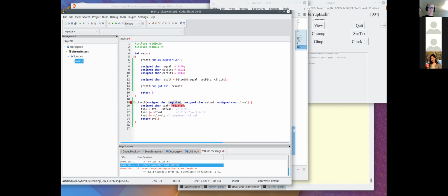So you can actually tell C that this variable belongs in a register. And we don't want to go there. So we're going to call this, let's say, HW register, because it's a hardware register that we're usually going to use this with, even though it doesn't have to be.